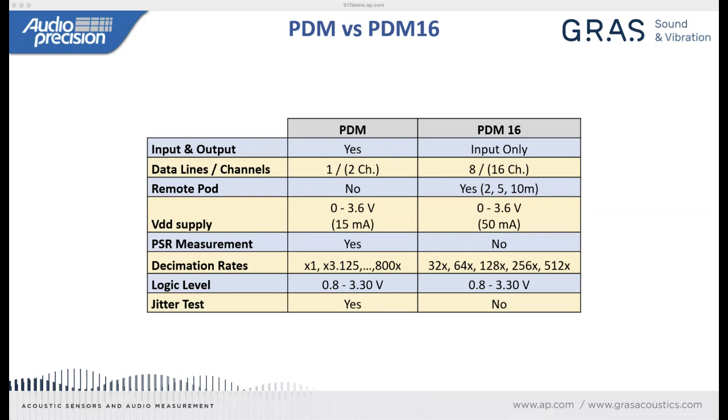I do want to address a question, which asks, power amplifier is mono. Can it play both outputs at the same time? The answer to that is no. On the 517, there is an A-B switch. There are 2 connectors for the power amplifier on the output. That's designed to let the 517 share 2 physical test jigs, but the actual power amplifier signal comes out of one or the other. Thank you for that question.